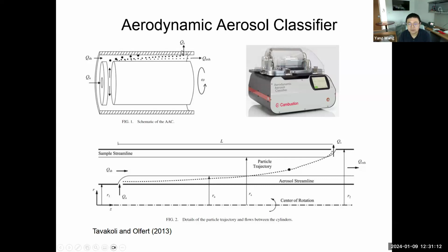And further, you could collect these aerosols, and then further measure their number concentration. So in this way, you can classify the particles based on their aerodynamic size and then monitor their concentration. One advantage of this aerodynamic aerosol classifier is that it does not rely on the charging of the particles, right? So particles can be neutral, and they can get classified just based on their inertia.